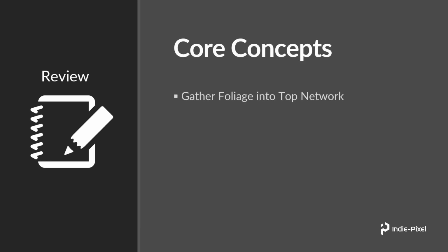learn throughout the section. We're going to learn how to utilize a bunch of file pattern nodes so that way we can gather different types of foliage from our Unity project, and these are going to be prefabs that we want to get a path to. We want that path because we want to then write it to a CSV file. So we're going to dynamically write our trees and our bushes and our rocks and stuff like that to a CSV file, and what we're writing is the actual path to the location of the prefab inside of our Unity